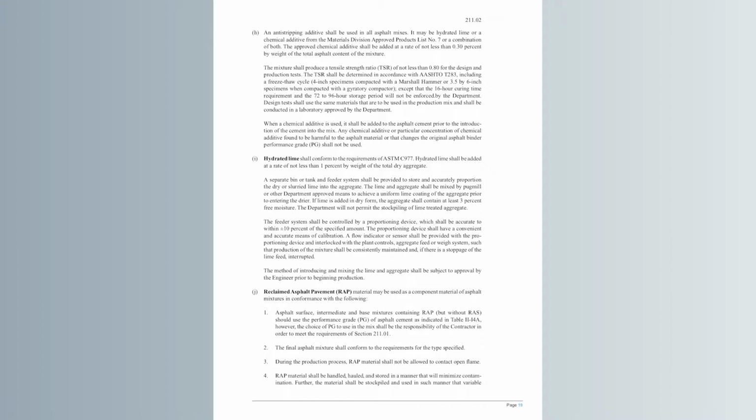Letter I talks about your hydrated lime. If you choose to use hydrated lime, it's added at a rate of not less than 1% by weight of your total aggregate. And it talks a little bit about how you need to add it into your plant.